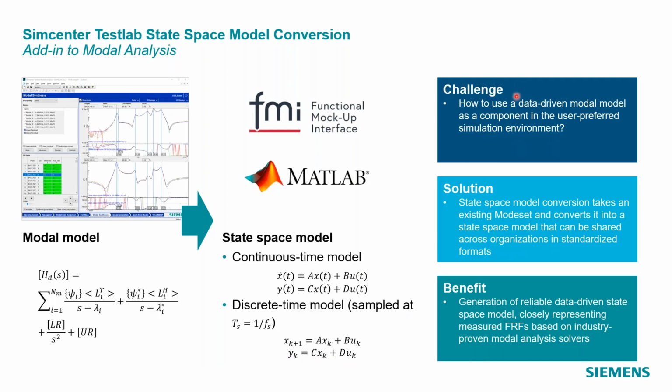And so the challenge here was to make a data-driven model that people could use as a component in an integrated simulation environment. Maybe like in my example, the shock absorber existed as a physical model, but I wanted to couple that to a data-driven model of the car itself that you could do with a state space model. So what we do, we take an existing mode set and we convert it to a state space model, and you can share it in your organization in a standardized format. And the export that we offer is either MATLAB or as an FMU, following the FMI standard. I will also explain a bit what that is about, functional mockup unit or functional mockup interface.